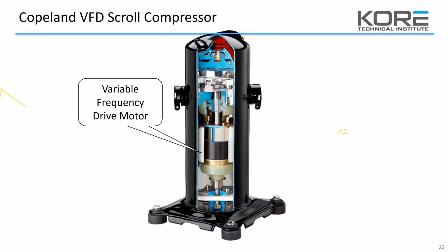So rarely will you see a VFD or an inverter on a scroll compressor. Now you can do it to a percentage, to a point, especially on a single system where you have one compressor and one fixed load, and you only need to vary that capacity a small amount. So they are out there. You will see them, but the speed throttling range of a scroll compressor is nowhere near what it can be on a piston compressor, on a recip,